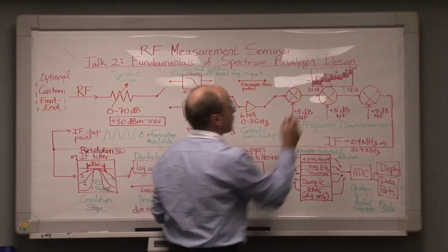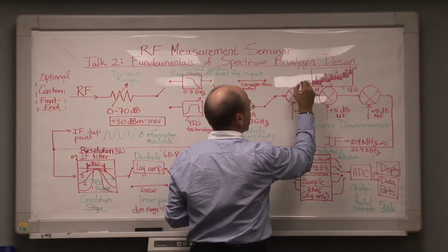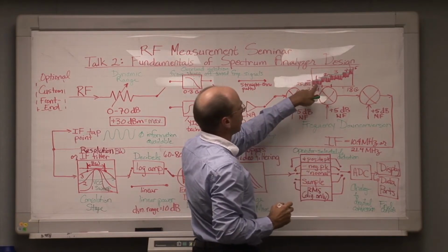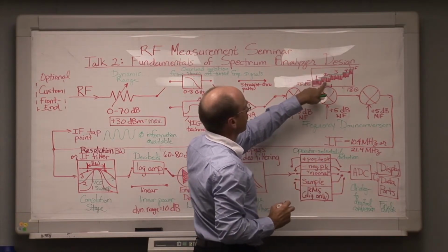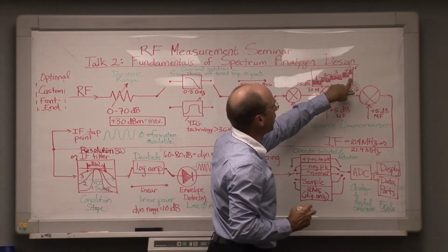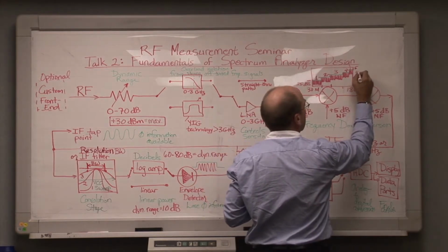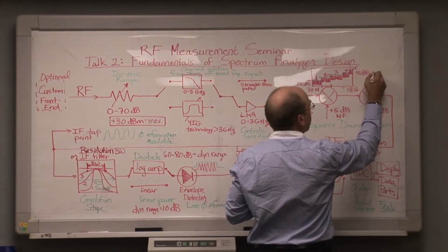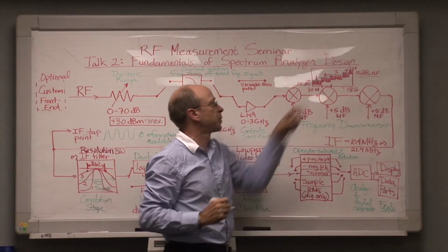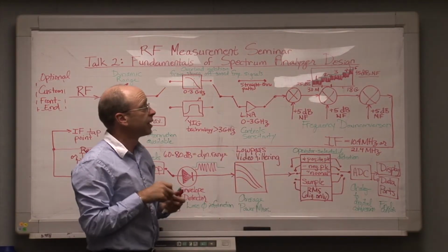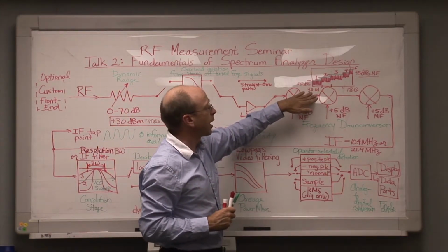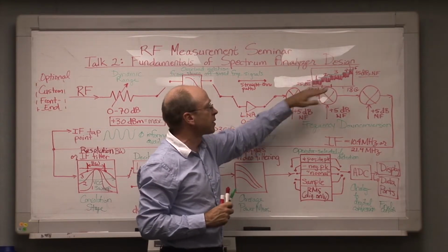And so we can see that although the spectrum analyzer might start with a 25 dB noise figure, let's say, here in this first range of frequencies, the noise figure here is 30 dB, 35, 40, and finally 45 dB noise figure by the time we get to the highest frequencies that this hypothetical spectrum analyzer provides. This is actually a very reasonable set of noise figures for a typical older analog system design.